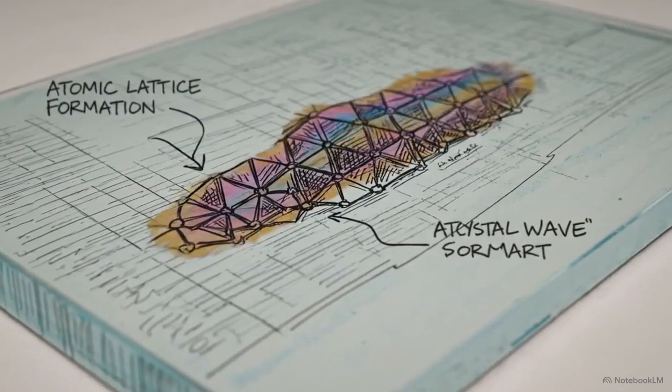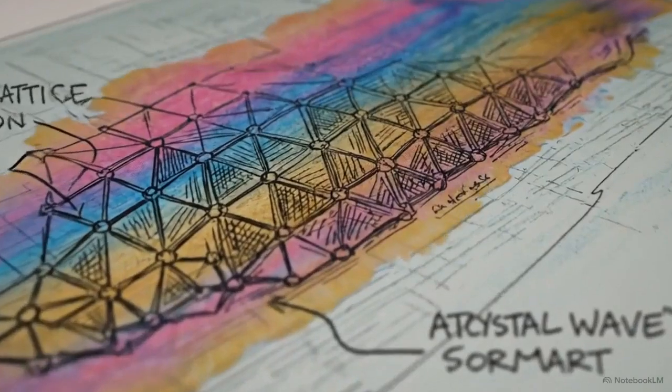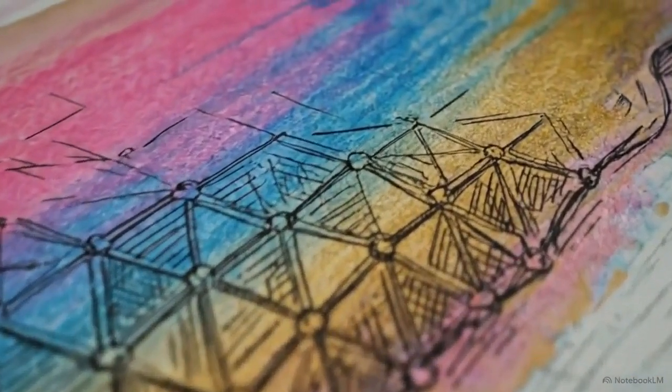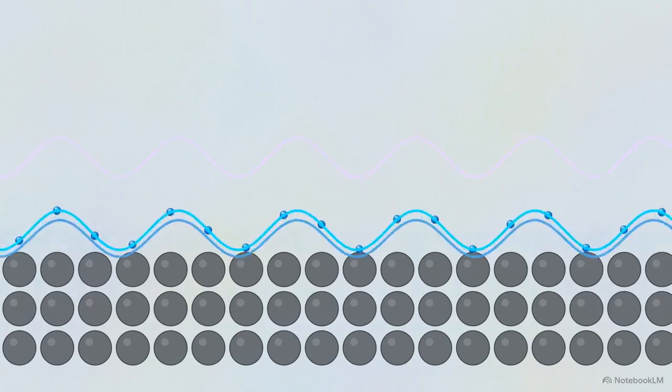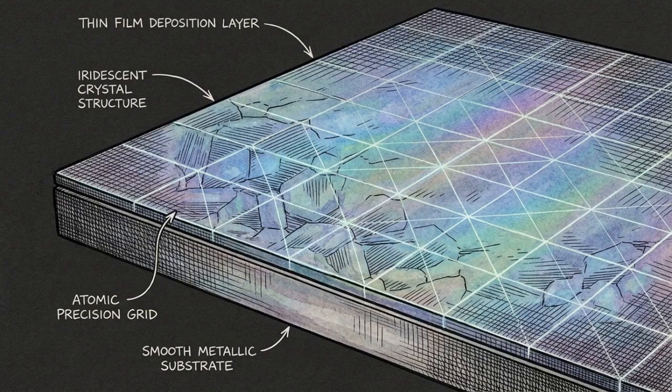To precisely dictate the optical transparency, iridescence, and plasmonic response of a surface at the atomic level, engineers rely on strict kinetic control. A plasmonic response is simply how electrons on a metal surface oscillate in reaction to light, determining exactly what wavelengths are absorbed or reflected. Achieving this level of tuning requires physical vapor deposition, or PVD, specifically the process of sputtering.